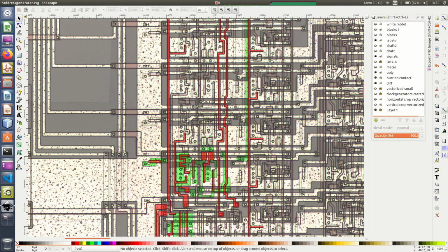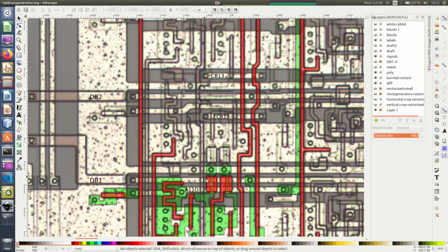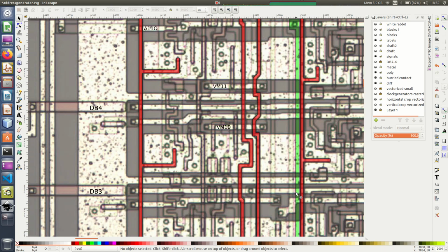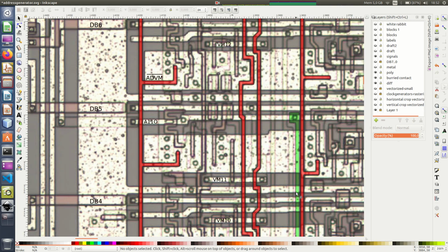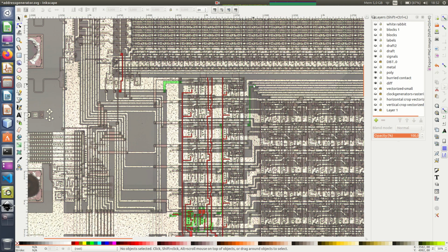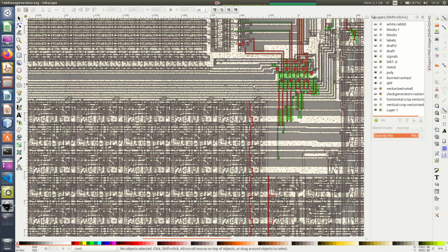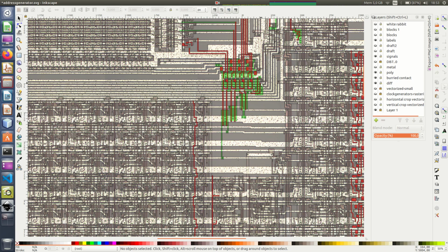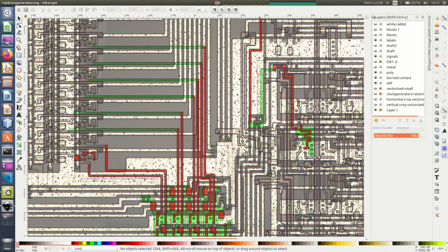The same happens over here. But we can also follow this line. It says A11 there, and I will show you shortly why it's called that. Then up here are the video matrix upper address bits. You can see they're connected together, so there is not only one driver on this network. If you follow it, it goes up here, the third from the top, and then up here, and you can see it splits into two directions. We have another driver here.